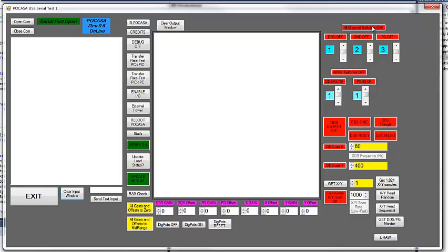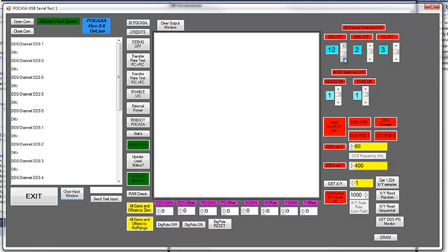Over here we got the channel switches off button, DDS channel ground. Pulse generator. DDS is direct digital synthesis. That's my sine wave out or triangle or what have you. Channel 0 through channel 15. So I got to make a deal that says if this channel is equal to this channel or this channel, then don't select that channel because you don't want any of them to be the same as the other ones. Bad things happen to the circuit itself.